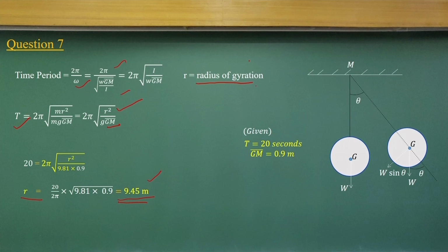Look at this problem. The ship is considered equivalent to a pendulum, oscillating at the metacentric height location, and if it makes an angle theta, then what are the restoring moment and the moment due to these oscillations? That is what we are equating to find out the r value.